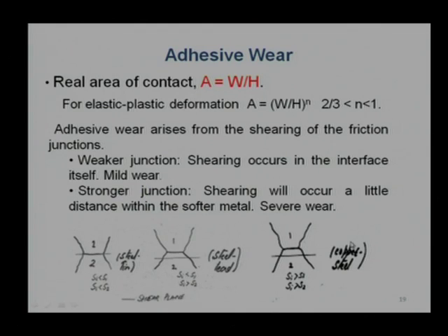That is why we say that we do not use copper and steel as such without treatment. If you treat them, increasing hardness and trying to reduce the adhesion between the steel and copper, then it can be used; otherwise it cannot be used as a tribo pair, as a sliding pair. The reason is the high wear rate between steel and copper. When they make an interface, the interface is much stronger than the copper strength, and higher compared to the steel strength. That is why we try to avoid this kind of pair.